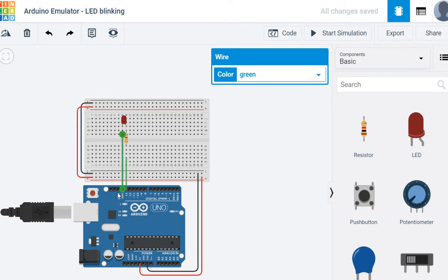And then I have the components connected in series going from pin 13. It jumps into the breadboard, and then on the breadboard you'll notice these highlight green, these little columns, because internally in this breadboard each of those columns are already connected. They're bridged together. So this is taking on the breadboard this wire to the resistor, and then from the resistor it's breaking into this little column up here that's connected to my LED in the anode. Then the cathode is in this other little column that's connected to a jumper cable back to the ground.